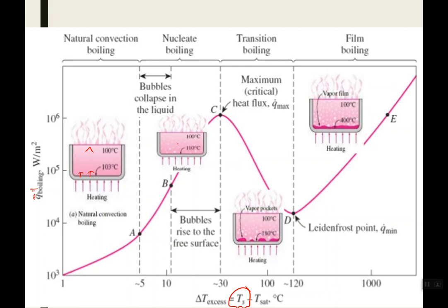Okay, Joseph, I do that every time. Okay, Joseph is saying you start to get a layer of, someone said air, this would actually be steam. So you start to get a layer of steam building up on the bottom. What that steam does is introduce a new thermal resistance from our surface into the bulk. We know that heat transfer happens a lot better in a liquid. Now you start getting these pockets of vapor building up here, which creates a new resistance to heat transfer.